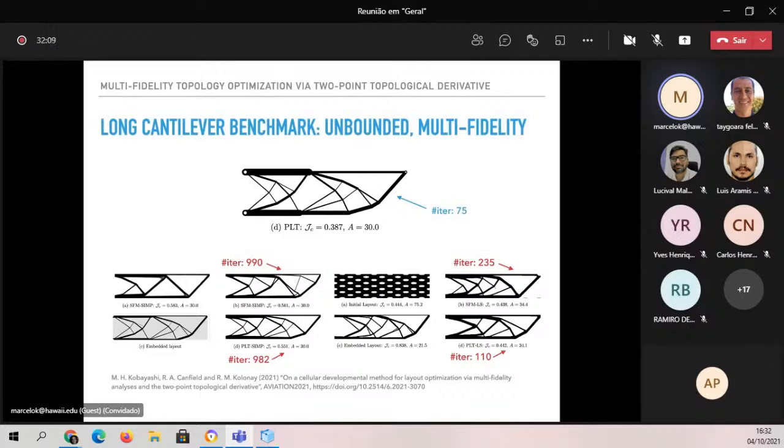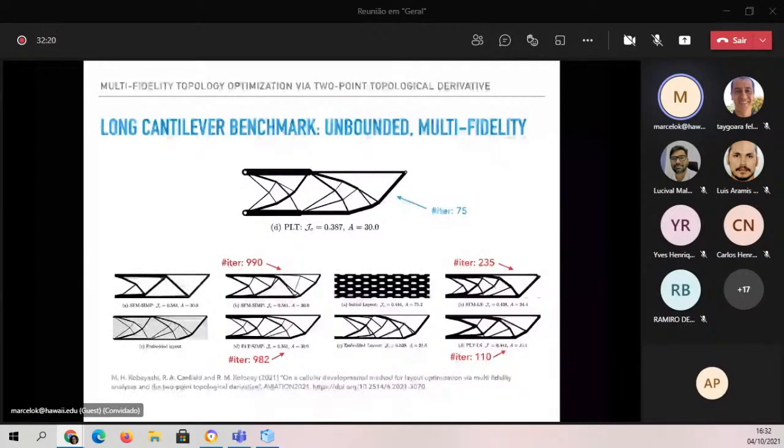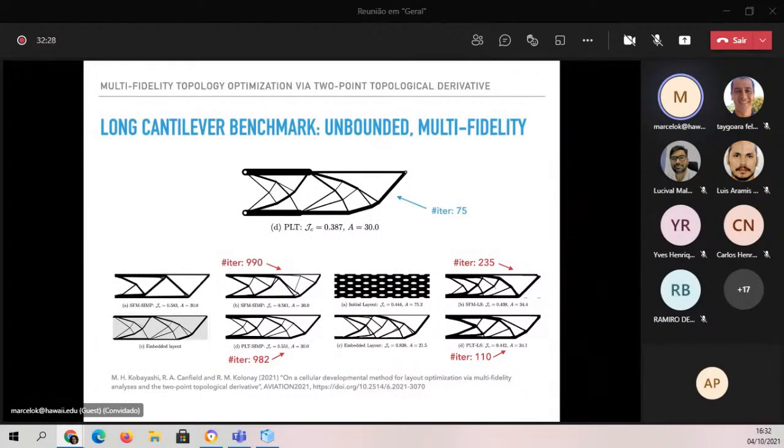Because if you don't have the geometrical thickness, you will not capture the complex stress distributions that you have at the joints. The usual assumptions for beam models, for example the Euler-Bernoulli assumption that cross sections remain unwarped and orthogonal to the directions, are not true in general, especially close to these joints. So we can capture the joints using the two-dimensional model in our method, starting from the solution that we obtained from the lower fidelity skeleton.